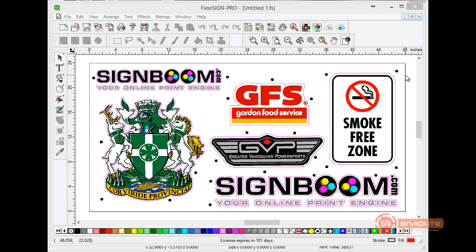number of devices. One of the things you'll notice on here are that in addition to the graphics, there are pink lines that represent the lines where we're going to actually cut these shapes out. And we also have little black circles on here, which are 1/4 inch fiducials. And these are the locations where EnRoute is going to send the camera. They're going to be little black dots on the printed sheet.